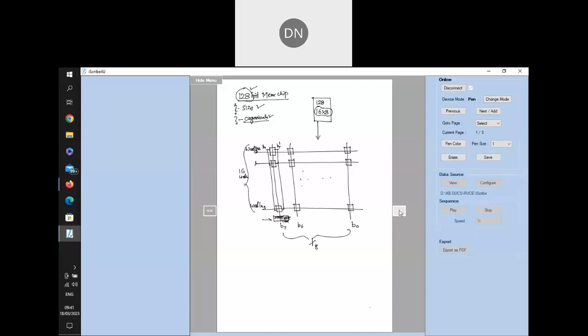It has the capability to perform reading or writing. That is why these sense and write circuits require a signal called read and write bar, which is generated by the processor. Also, since multiple chips are present inside a computer system, not just one chip, there is also a chip select. So these are the two signals which are connected to the sense and write circuit. These circuits are present everywhere.